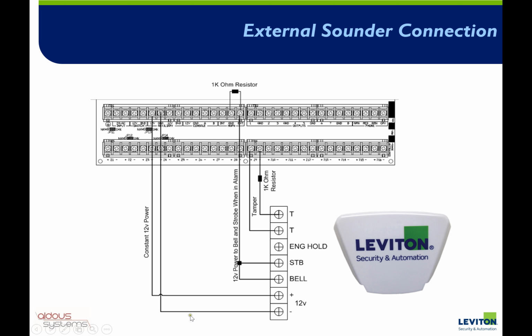If it's ripped off the wall, then it will detect its power loss, and it will start sounding immediately based on its battery backup. And also the tampers will trip, informing the Omni that it's been tampered with, and put the Omni into alarm as well, and dial out and call the monitoring station or call the owner and show tamper on the touchscreens and the like.